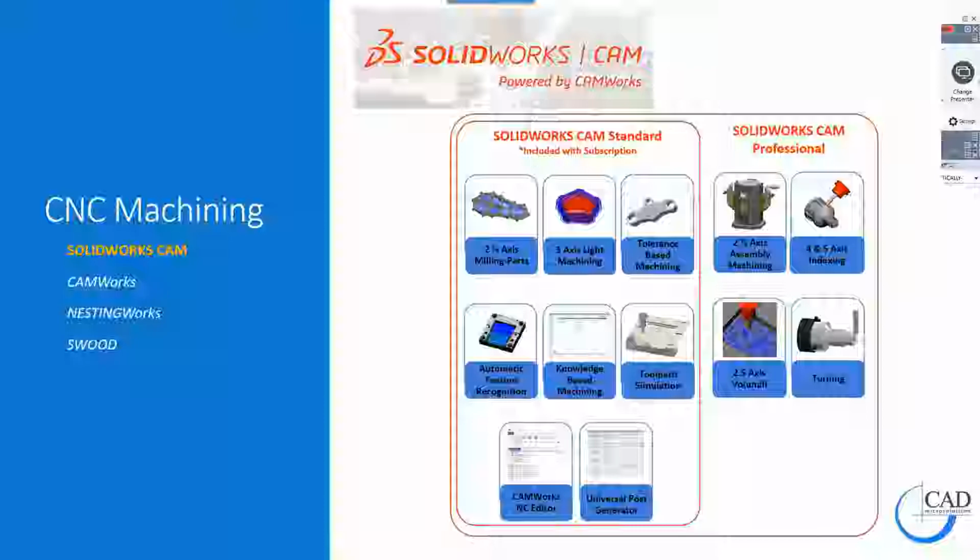So let's say, for example, we're looking at a specific size pocket on a specific material. If we're cutting that pocket in steel versus aluminum, we're going to cut those differently maybe. So we might use a couple different roughing tool paths and a finishing tool path, whereas in aluminum, maybe we only use one roughing tool path. So we can actually teach the software how to strategize those tool paths. We also have simulation inside that standard version.